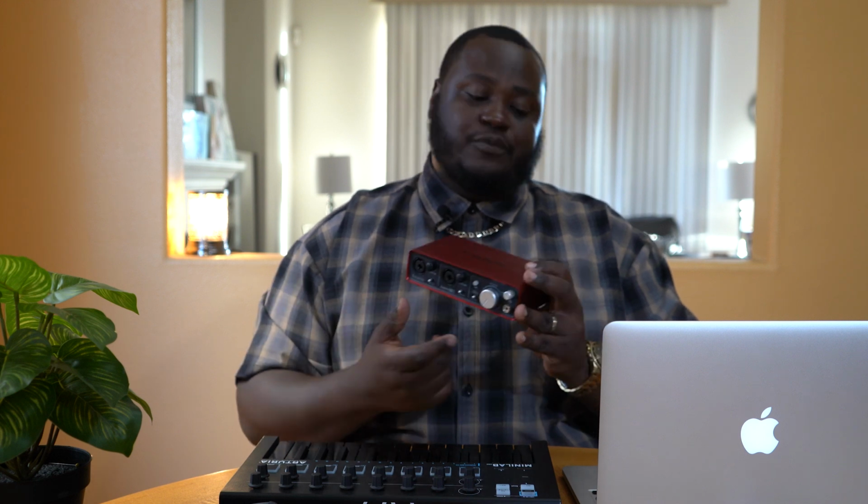An audio interface is a device used to bring audio into a computer as well as to bring audio out of a computer, where it can be monitored either through the headphone jack or through speakers that you connect to the audio interface. This is the Focusrite 2i2 audio interface. It will allow for two inputs in the front via these combo jacks, as well as a monitor output and a headphone input. And it also has phantom power that you can enable if your microphone or device requires phantom power. You can learn more about devices like this on our channel.